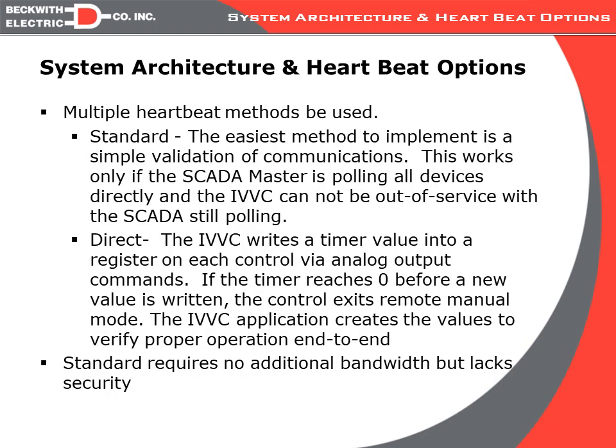So, we have two different heartbeats we can deploy. The standard heartbeat is the easiest to implement. It's one setting on the control, which is the time value, and the time starts counting down, and as long as we receive valid communication from the SCADA, we automatically reinitialize that timer.